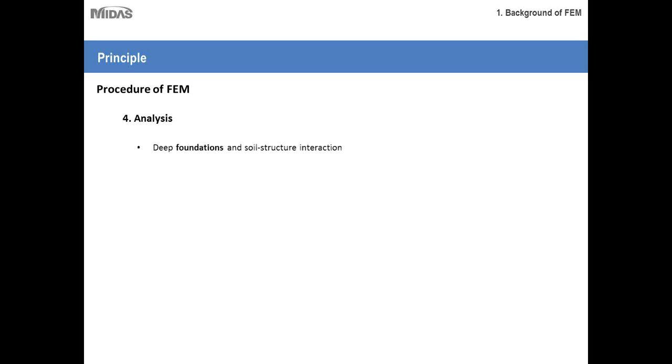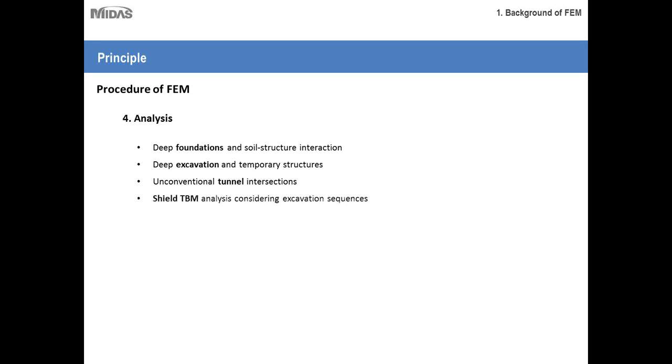So finite element method is found very helpful for the following types of analysis, such as deep foundations, where you definitely need soil structure interaction, then deep excavations, where you need to analyze the forces in temporary structures, then unconventional tunnel intersections, where you have to see the stresses as well as displacement in the connecting galleries or the junction points, then shield tunnel boring machine analysis for considering excavation sequences, vibration analysis for earthquake and blasting situations, slope stability analysis, consolidation analysis, groundwater flow.